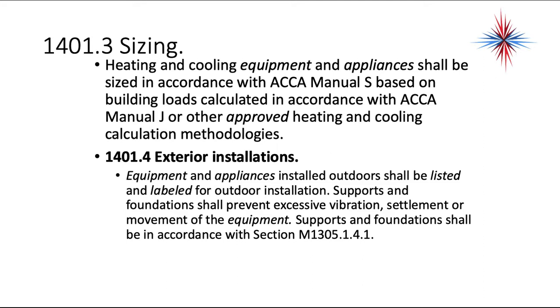1401.4 talks about exterior installations. Equipment and appliances installed outdoors shall be listed and labeled for outdoor installation. Supports and foundations shall prevent excessive vibration, settlement, or movement of the equipment. Supports and foundations shall be in accordance with section 1305.1.4.1. Again, we're referencing other sections in the code.